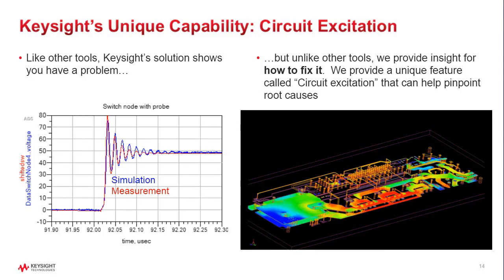And this is not extremely difficult for general purpose EDA tools, but what Keysight has as sort of a unique capability is the ability to excite the PCB under operating conditions and then see how it behaves in the electromagnetic environment under operating conditions. So we refer to this as insight, where you're looking at things like on the right, you should see an animation of the surface current density on a couple different layers of a PCB. And refer to that as insight.